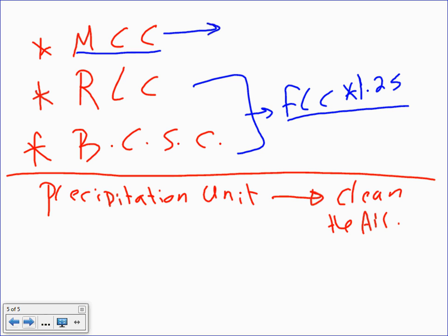And we're talking about cleaning the air, guys, of toxic fumes and flying particles that could hurt my friend Holly if she's a worker on the manufacturing floor breathing all these toxic fumes. So they take the air and pass it through a unit. If you look at the really nice example on page 178, they have a blower, and the blower blows the air through this unit, and the unit has ionizer and collector cells.